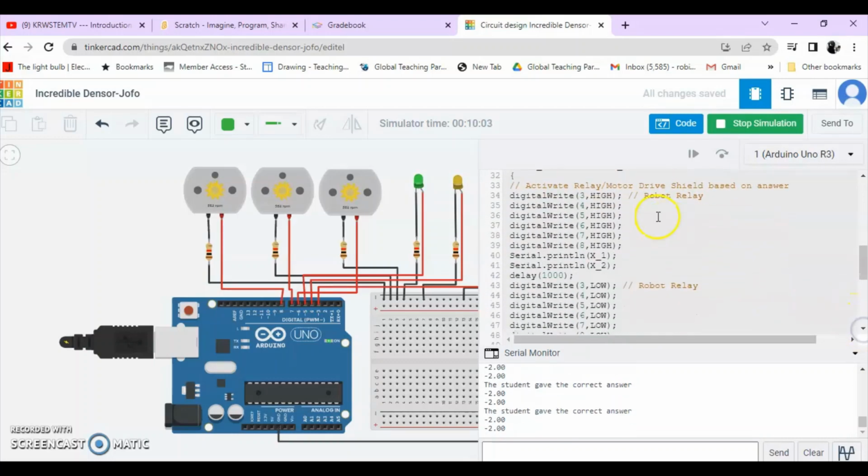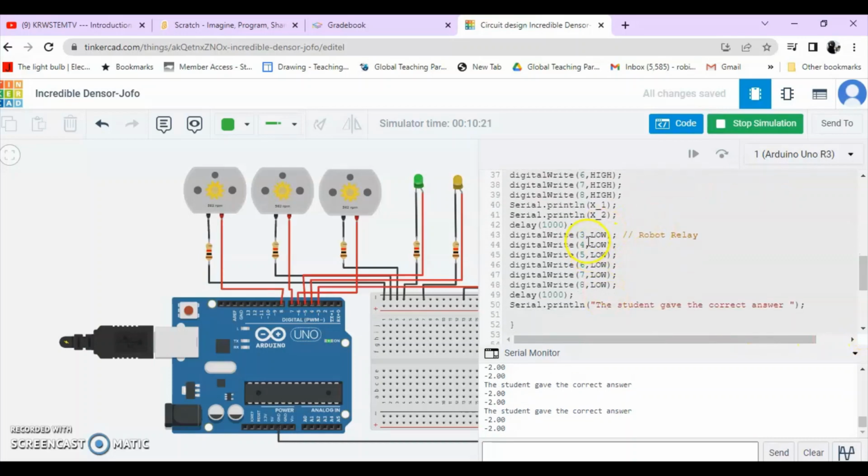And of course this is how we choose to control our devices. We have 6 devices, and up here we are writing 5 volts to each of these pins 3, 4, 5, 6, 7, and 8, and that's high. And then down here we're writing 0 volts to the pins. So 0 volts means that we're going to be turning off the device. Alright, so that's the concept.